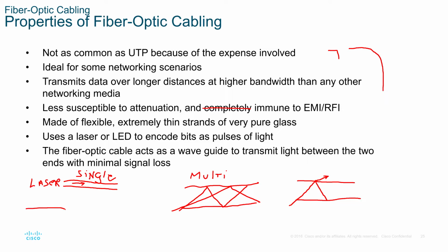You can have what we refer to as just a micro bend, just a sag in the cable. And as the signals come in, the angle changes so that we do lose some light. So this is a natural occurrence that you cannot totally eliminate.